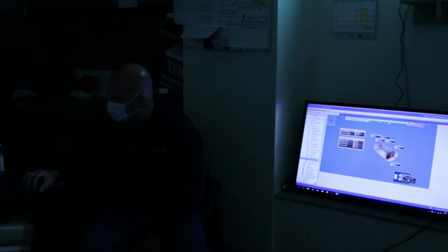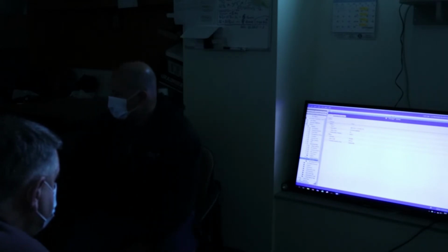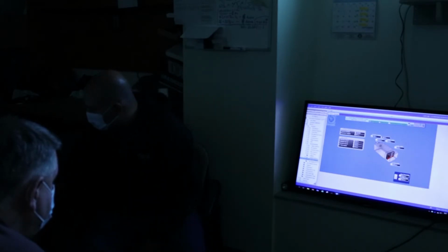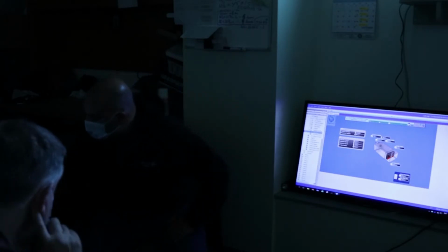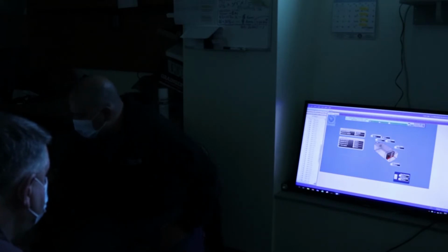So if we go to, let's see. This doesn't have a trend. We have to do the trends from the tree, right? So if I highlight the point, it tells me where it is. So it's in NAE5 FC2. So if I go to the tree, go to NAE5, FC2, and I want to pull box number 1510. So 1510, I expand that.